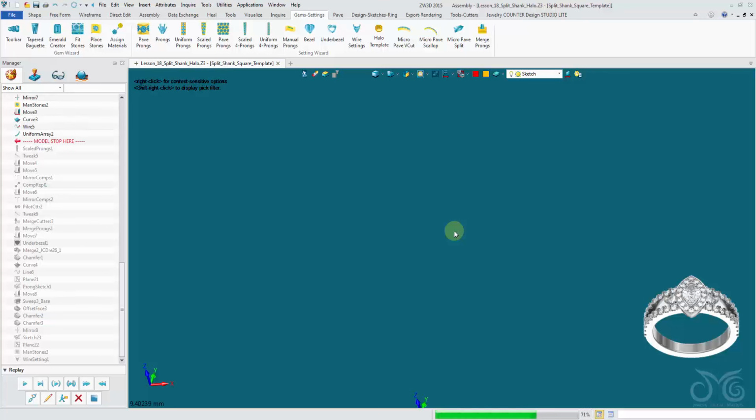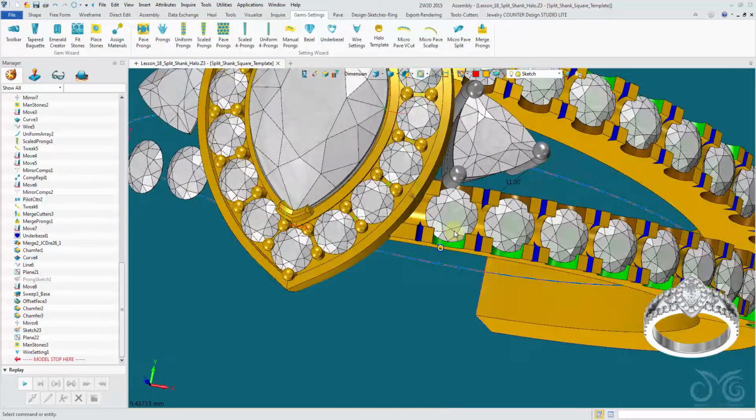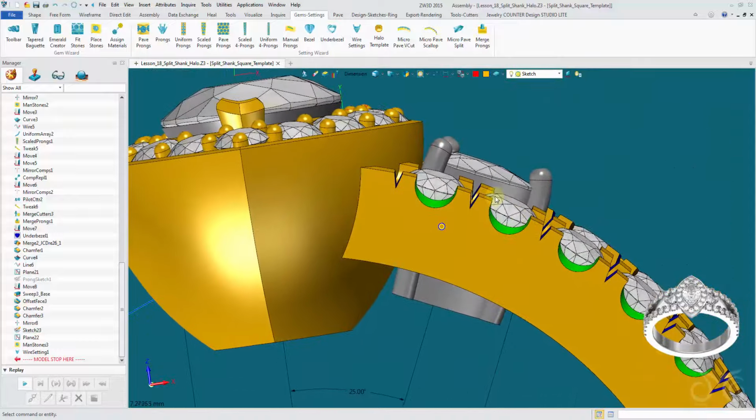Okay, we could by this stage drag our feature frozen bar down to freeze our history so that the regeneration doesn't take quite so long. Okay, we've moved it up. Okay, maybe I've moved it up too far there.